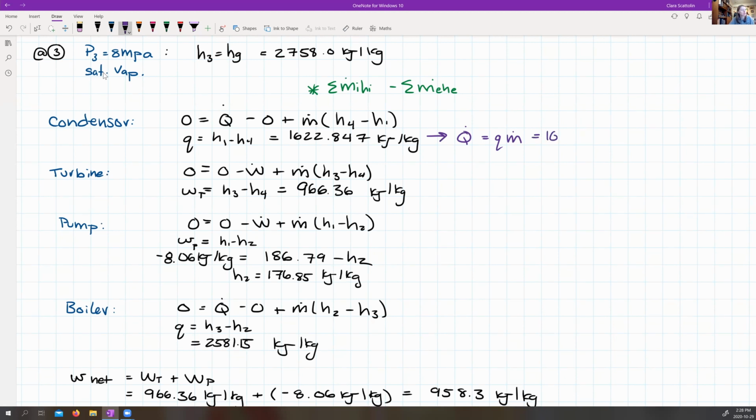So the condenser here was 1622.84 kilojoules per kilogram. I'm going to use our value in per second because it was 104.35 kilograms per second. So again, if you check my units, I'll get kilojoules per second, which is a value of kilowatts. I didn't actually compute this, so I'll do that quickly. All right, this will give us 169,343 kilowatts, because a kilojoule per second is a kilowatt.